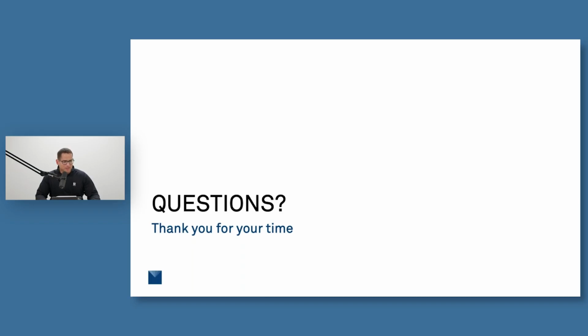Okay, that's somewhat not a fully loaded question, and I'm not sure if this is referring to the field measurements with sensors installed or the measurements with a device to measure hydraulic conductivity, but typically if your site is actually completely saturated, you're going to see no movement of water into the soil because at some point it does stall out.